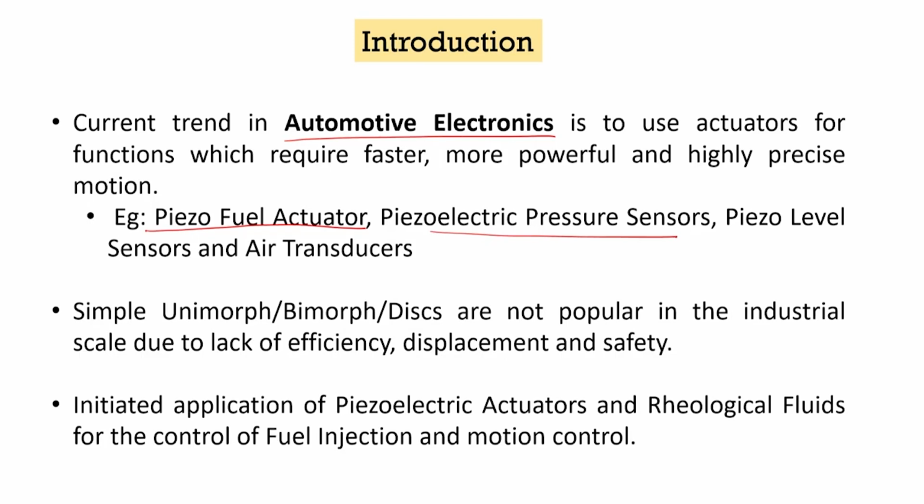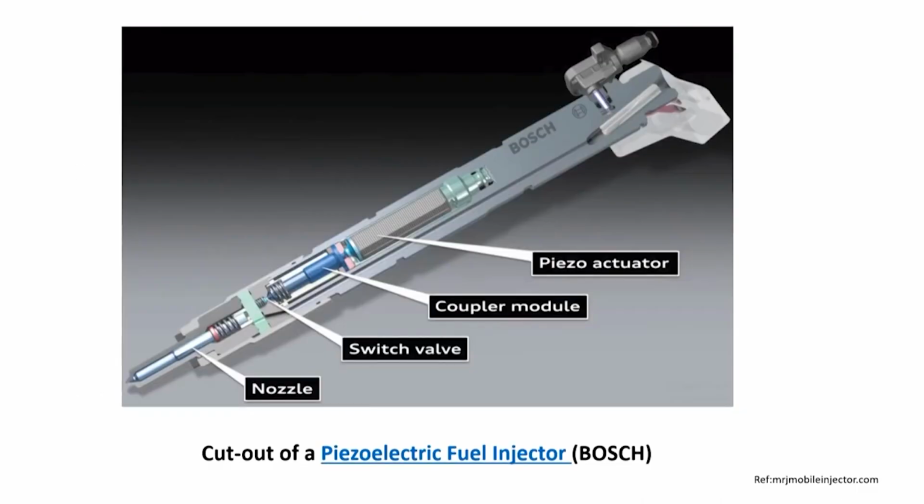So, this is one way the stacks work in an axial direction, but if you want to produce some kind of bending, etc., then you have to use unimorphs, bimorphs and all these things, but they are not so popular because of reasons of efficiency, lower displacement and safety, etc. So, mostly the piezoelectric actuators and rheological fluids in a stack mode are used for fuel injection and motion control in automotives.